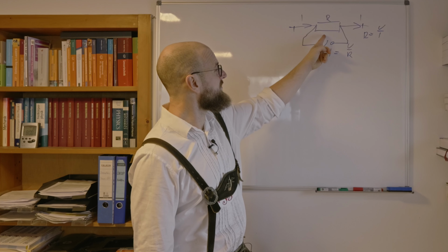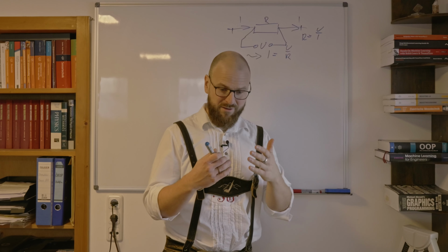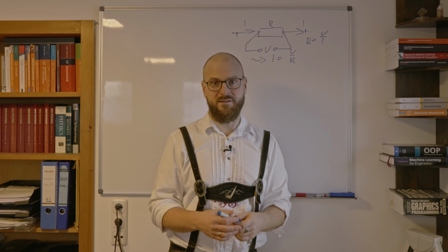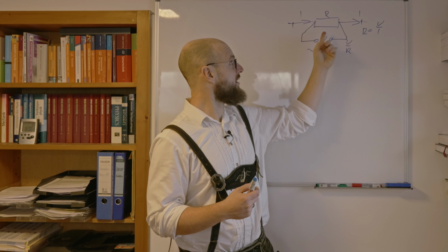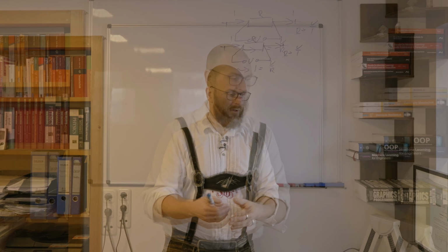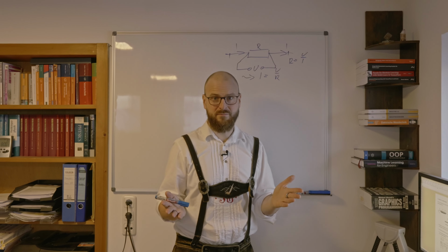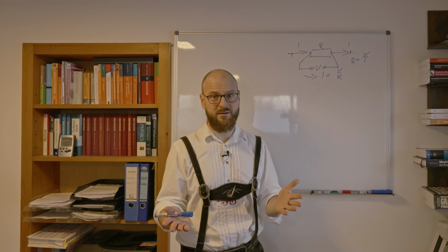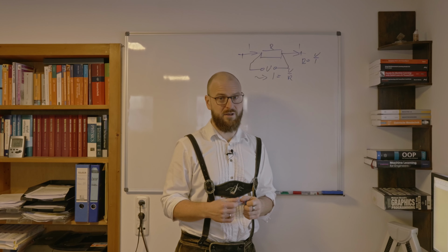And now we still have to measure that voltage in direct vicinity of the ohmic resistor. The ohmic resistor will get warm for sure. And moreover, we have those high currents which we have to connect to. So there's no galvanic isolation and we are in direct contact with the current. That's the main problem about that way of measuring currents.